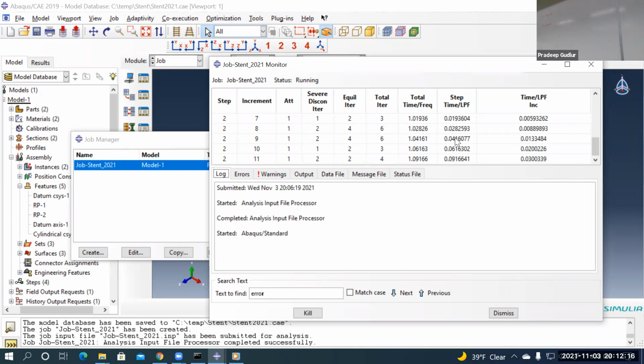So it's taking bigger increments now, but it's slow. You have errors? Yes, let's see. Errors are good, so you will see what the problem is. Missing property definition, so you didn't use the material property. So let's see the solution there. I could find the solution for property.